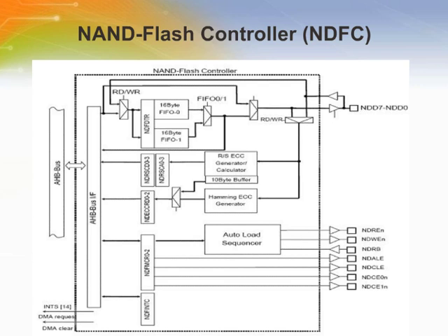Includes an ECC generation circuit using Hamming codes for the SLC type. Includes a 4-address 4-byte error detection circuit using Reed-Solomon coding/encoding techniques for MLC type. Provides an autoload function for high-speed data transfer by using 32-bit by 4-word first-in, first-out registers together with a DMA controller.